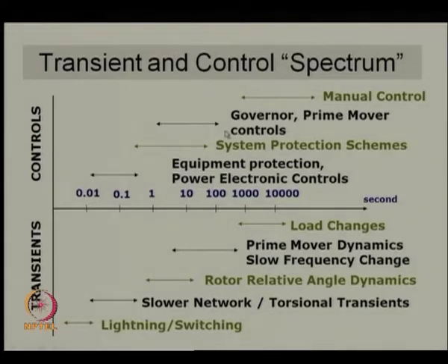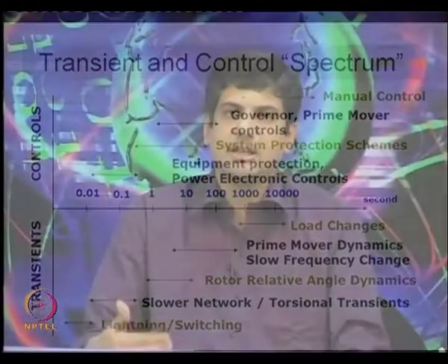You also have other control systems, like for example, the excitation in a synchronous machine, which is controlled by what is known as the automatic voltage regulator. That also you can consider as acting in the range of 0.1 to around 1 or 2 seconds. Okay. So, that is the typical response. I am deliberately not giving too much precision into what I am trying to say.